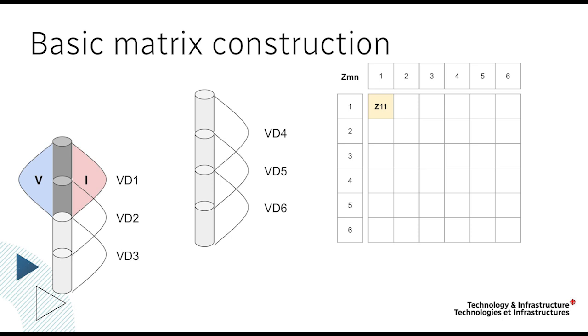So you see the first V dipole, if we cursor, yes, I have a cursor. The V dipole here is imposed a current of 1 amp, and then you have to measure the potential that 1 amp creates on that segment. So it just integrates the field strength that 1 amp creates. If you integrate field strength, volts per meter, over a distance, meters, you get volts. And then you divide your volts by the input, which was 1 amp. If you divide volts by amps, you get resistance or impedance, because we're in RF. And you repeat the process all over again 400 times, and you fill the matrix.